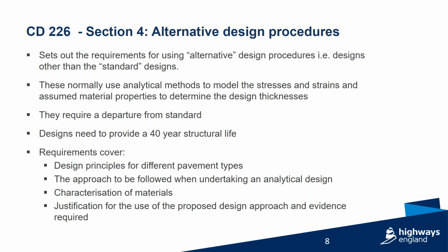Section 4. Alternative design procedures. This section sets out the requirements for using alternative design procedures, for example, designs other than the standard designs. These normally use analytical methods to model the stresses and strains and assume material properties to determine the design thicknesses. They require a departure from standard, and designs need to provide a 40-year structural life.